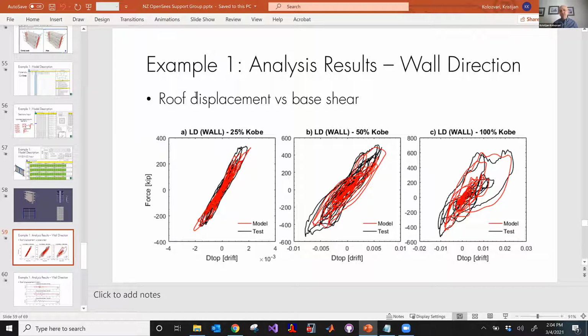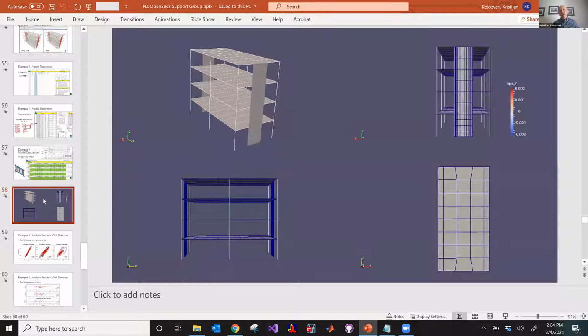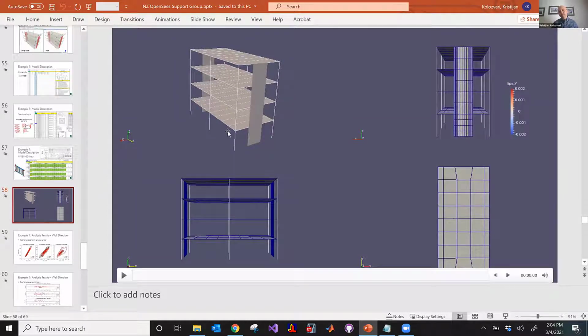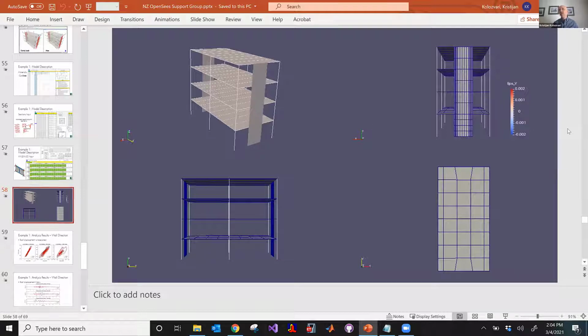One thing that made some difference was that this is now a 3D building, right? So all the elements interact. So the stiffness of the slab actually makes some differences. We're using, if I remember correctly, quite small out of plane stiffness and cracked shear stiffness. So we did run some sensitivity in terms of that parameter. In terms of the actual wall element, no, again, it all comes down to the materials.